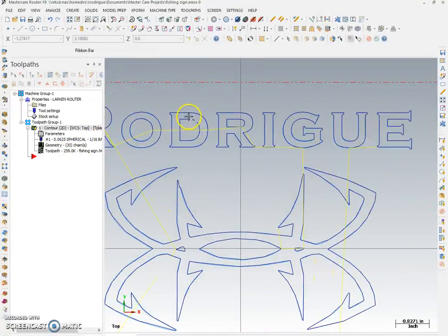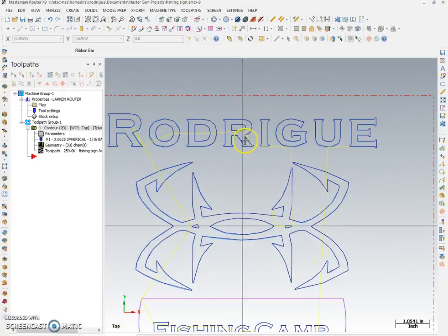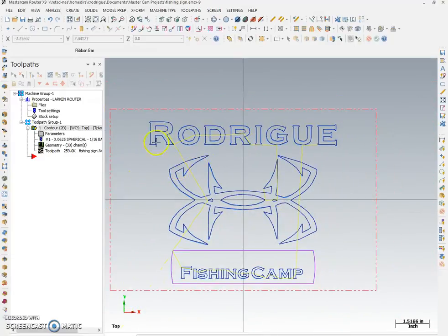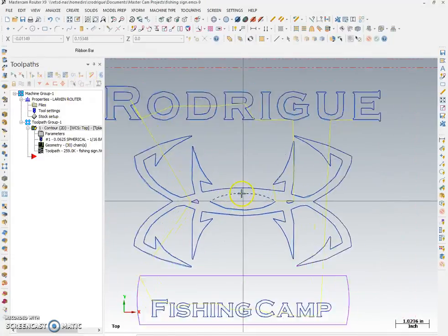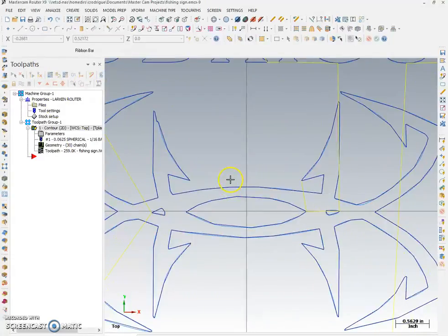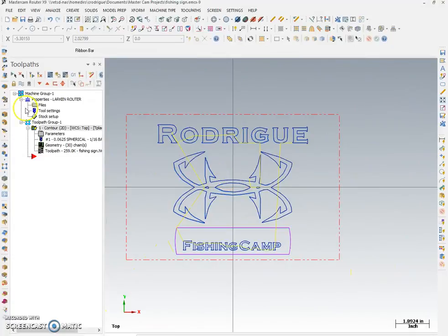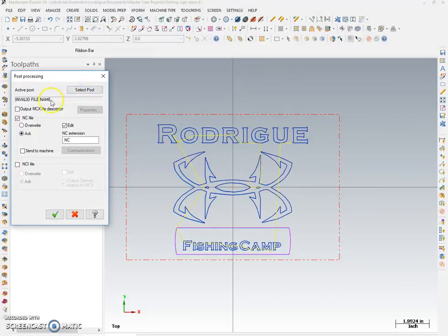So you always hear about people doing code and coding. This program is going to do a bit of coding for you. It's going to turn it into X's, Y's, and Z's in relation to where it is on the page, and that's all it does. It actually turns the whole thing into a series of lines of code, and it tells the computer to move the cutter to X this, Y that, Z this, and it'll go ahead and take you to that point. So we go ahead and push that G1.